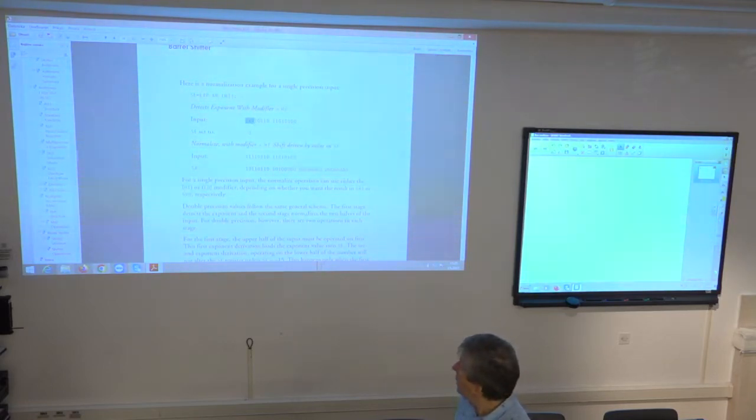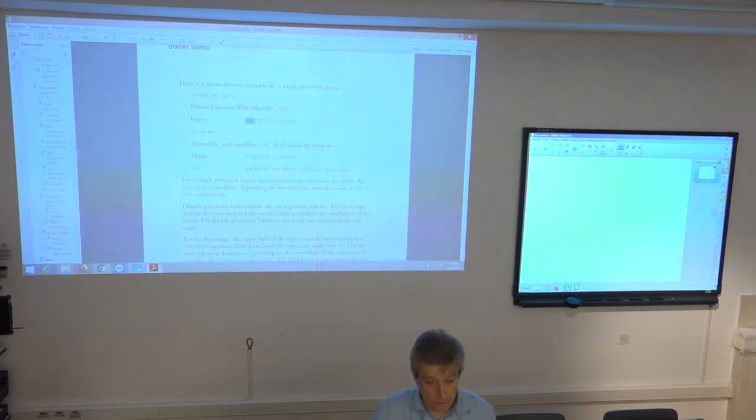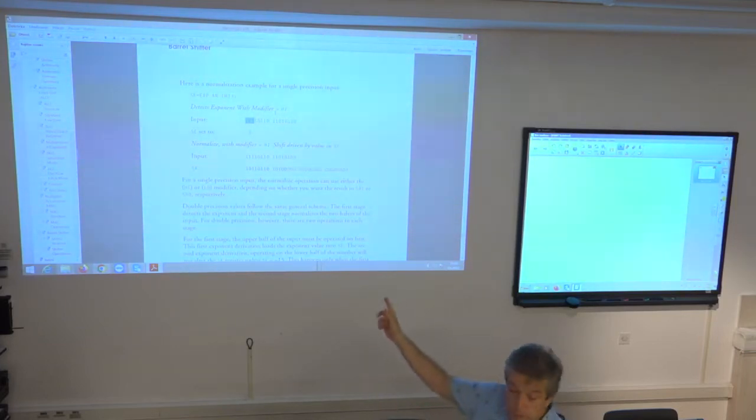And then with this instruction, exponent of AR, I will finally have this value -3 stored in this SE register. After negation, this value can be used for normalization. So if I use the norm instruction after this one, it will simply take this -3 value, convert it to +3, and then perform a shift by 3 positions to the left, and you will have normalization of the input value in 2 assembly instructions.